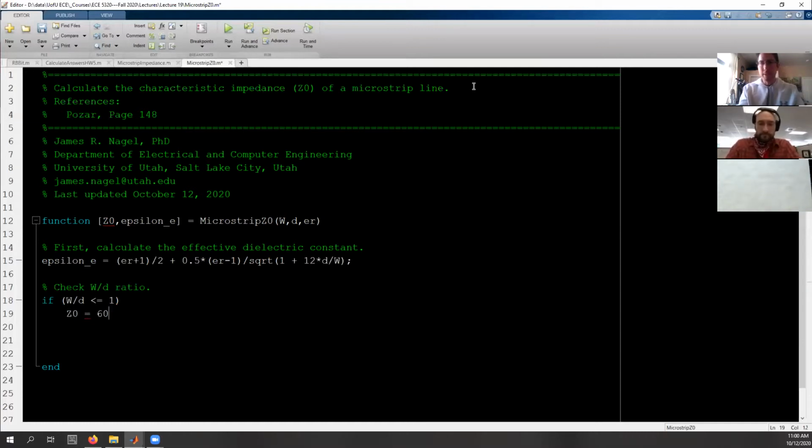So you say 60 divided by the square root of my effective dielectric constant, times the natural log of 8 times D over W plus W over 4 times D, like that.